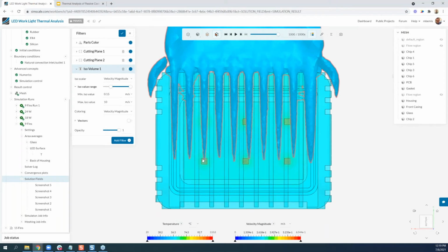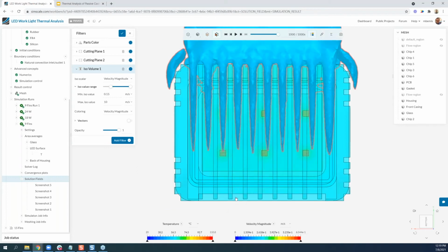Regardless, if you look at where we hit this 15 centimeters per second or higher in the vertical direction, I'm really happy to see that this starts pretty much in the same place the whole way down. It'd be great if we could get a design where we have the high velocity come all the way down to the beginning of the heat sink. Again, gravity is down on this, so we're looking at it as if we're staring at it head on. Gravity is down, but it takes some distance to develop a thermal plume here.